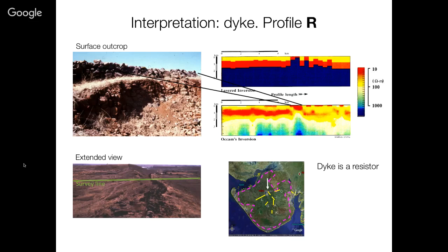And yeah, there's a few details. One is on a particular line profile, we ended up with an image that looks like this. So here is that sedimentary package. It kind of peters out here, and the resistive region underneath comes up. Initially the question was, what was that? They went out and looked, and said, oh, there's a dike up here. Turns out to be a resistive dike.